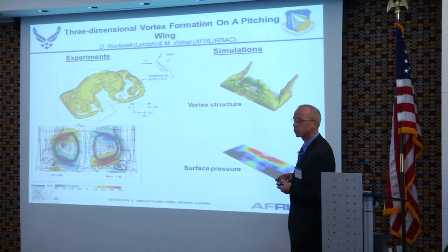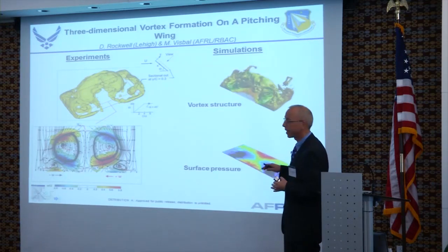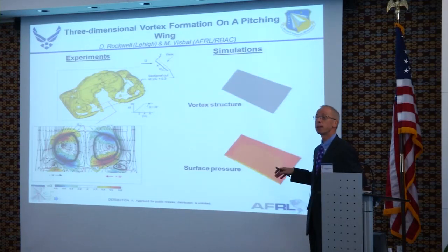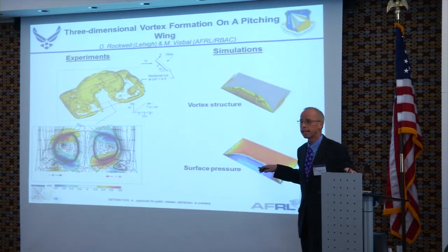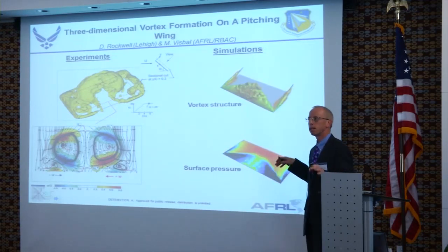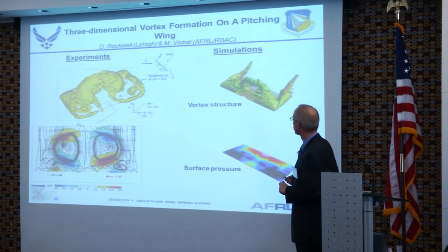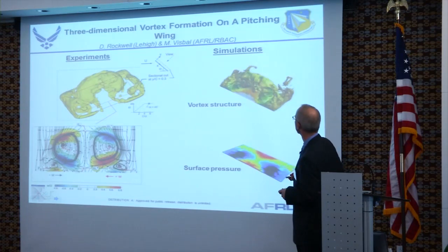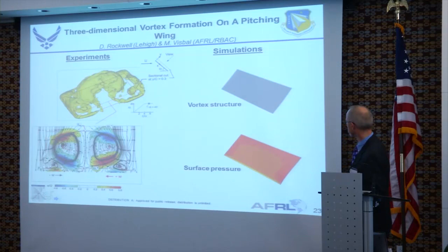But what this is showing us is what the structure of the separation of this flow field looks like when you're getting this sort of rapid pitch up. This would be a motion that would be, say, representative of a bird coming in and trying to perch. It's coming in, flying, flow nice and attached, and then it rapidly pitches up and creates a lot of drag, and it slows down and sort of drops down in. So Don's got the experiments, and they have really good comparison with the simulations that Miguel's got. So that's exciting.